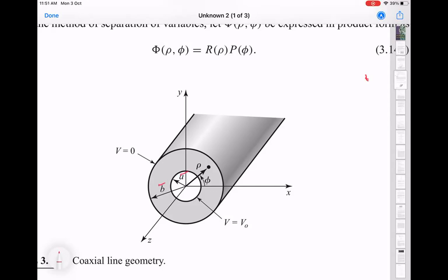In terms of electrical transport, you know that currents usually flow on the surface of the metal, right? So the thickness of the outside shield, because it's a hollow cylinder, in some sense doesn't matter so much unless it becomes so thin that it starts to affect the resistance per unit length of that particular material. So usually the thickness of the outside doesn't play a role in the properties of the system.